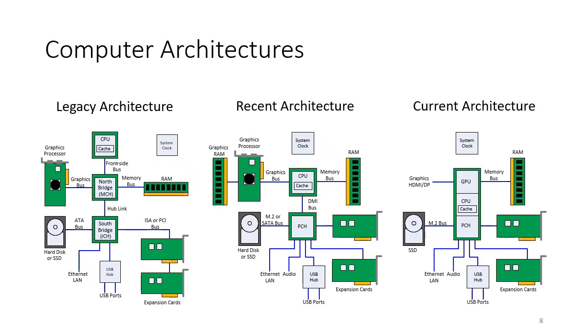The clocks themselves, of course, are also a lot faster. And another thing about the clock is that increasingly with modern CPUs, the clock is variable, because the CPU itself can change its speed according to what workload it needs. So when the computer's heavily loaded, it will be running at a higher speed than when it's lightly loaded, in which case it can slow down, and that reduces the power consumption and reduces the heat. There are a lot of other aspects here which are getting a lot more complicated in modern devices, but all of this is helping us by improving the performance we can get from these modern components.